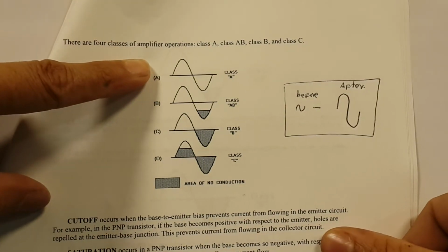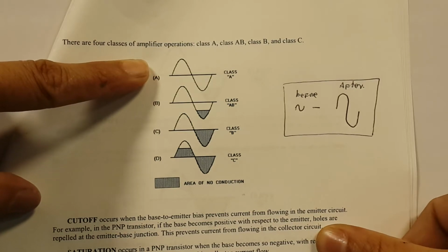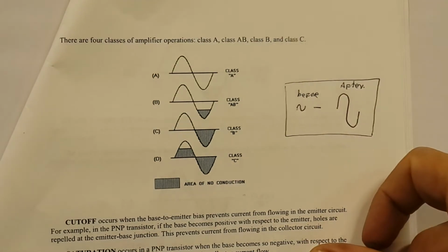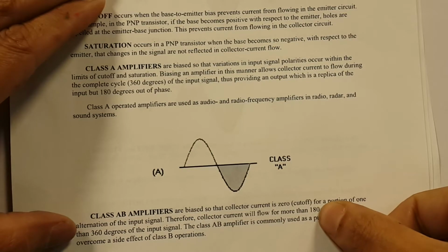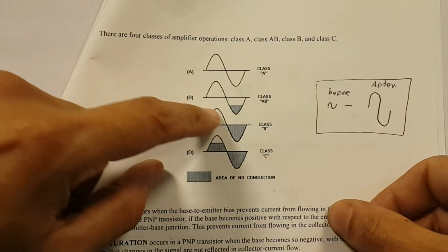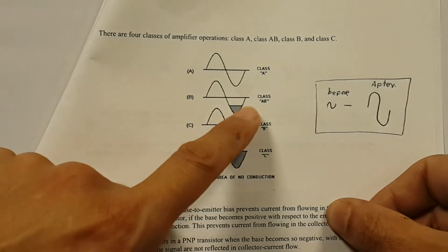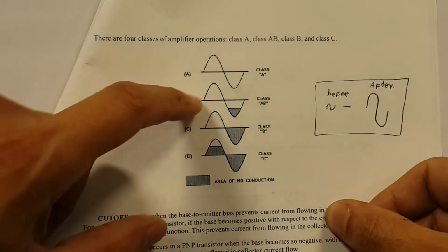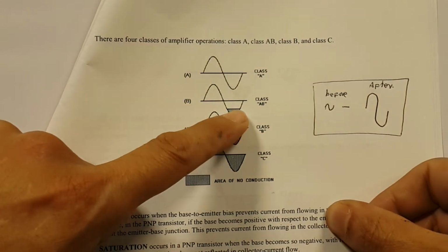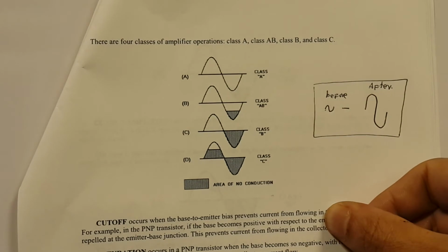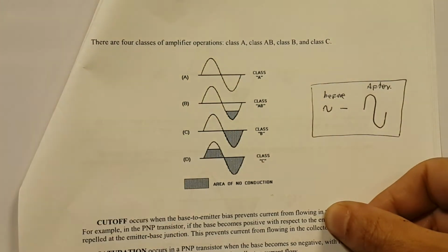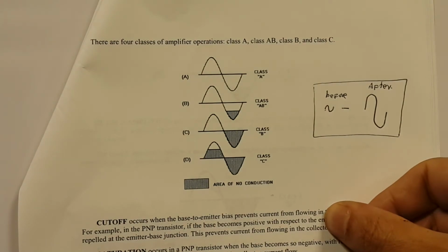They use a lot of power, so they are said to not be very efficient, because they are conducting the whole time, but they have high fidelity. Class AB is described as a transistor that conducts for greater than 180 degrees, but less than 360, and that is represented by here. It's designed so that it will cut off. Cut off means it will not conduct for that part of the signal. So it will conduct for the majority of the signal, but it will cut off for one little area. A little bit of information is lost over here, but it is okay for this type of transistor, depending on the application that they are used for.